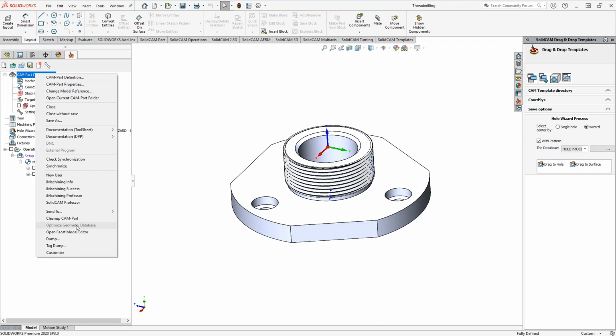But if you come in here and are running an older project, maybe from 2018, and it's taking some time to open and close along with saving calculation, click this. You'll see it removing geometry tags and then reapplying new geometry tags.